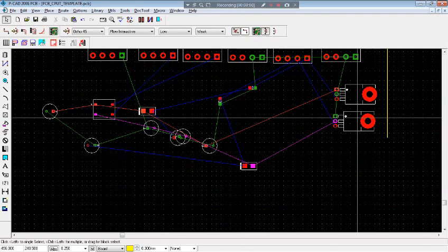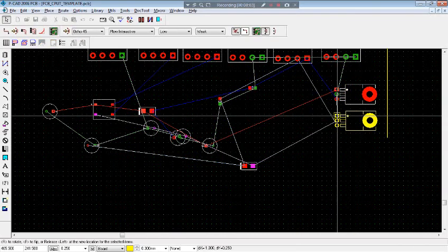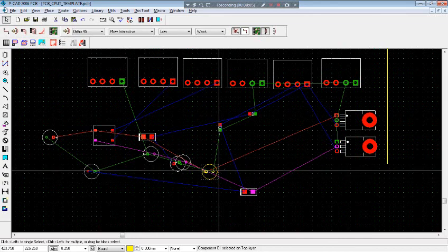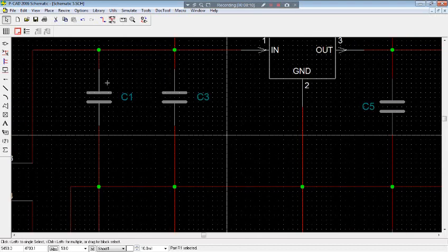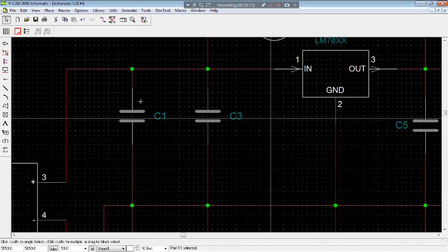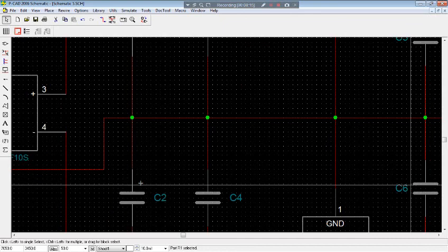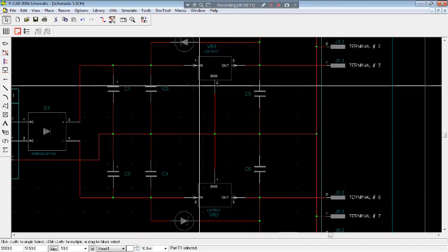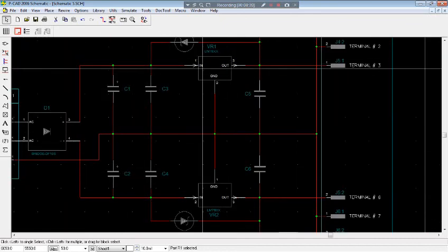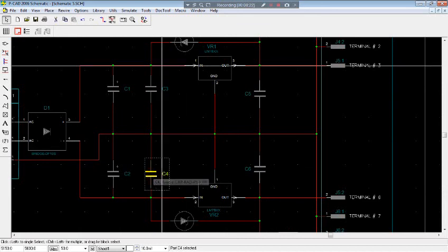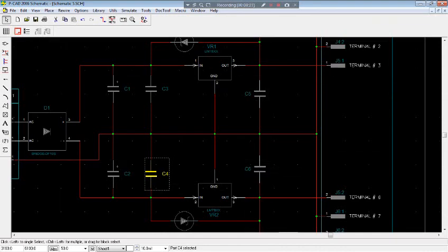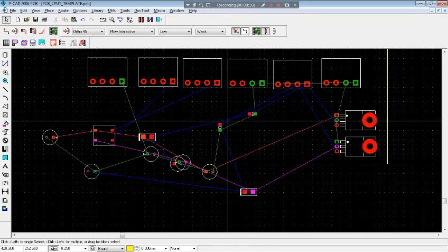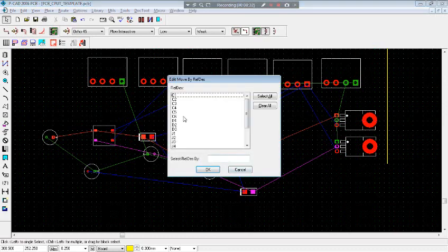I know that this is my regulators. Move those there. And next capacitor, I think, which was the closest one? Back to schematic. You're going to see a lot of this back and forth. Okay, so recognize that that's C3, C5, C4, C6. As I said, start with the smallest ones, but generally I look at what's closest around it in the schematic. See that's closest? C3, C4, C5, C6. Back to PCB. And let's press F5 to place by reference. That was 3, 4, 5, 6.